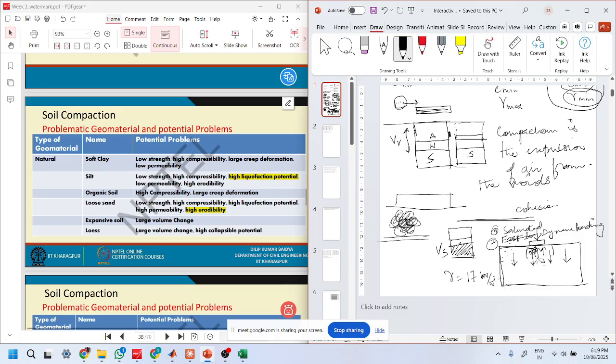It's not a problem. But anyhow, if you provide dynamic load in such a way that you don't give enough time for the transfer to take place from water to soil skeleton, as in machine loading or quick loading, this will behave as if it was a surface of water, because that is what is retaining your weight down. It's not the soil. Soil particles are literally floating in the water because the reacting force is equal to the weight of the soil.